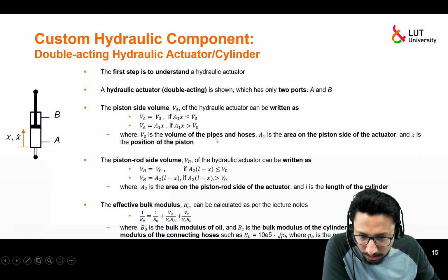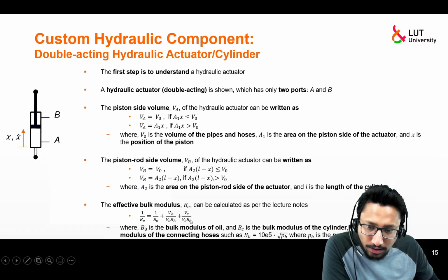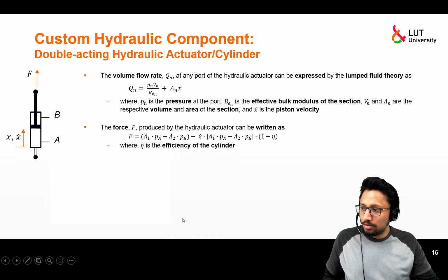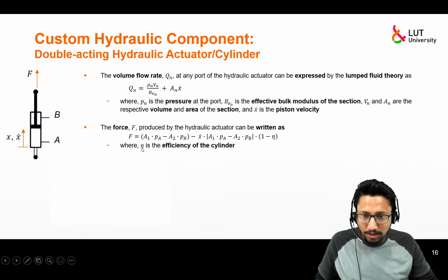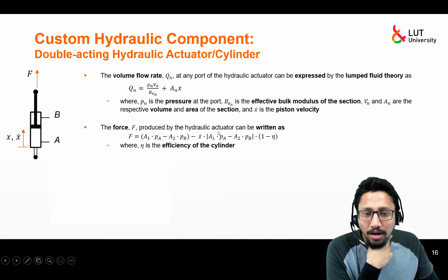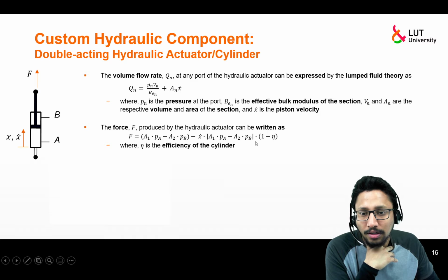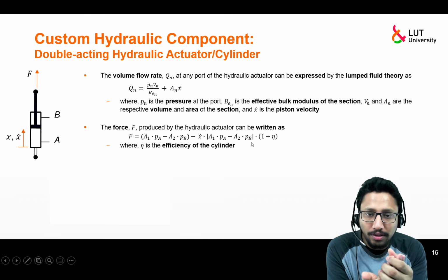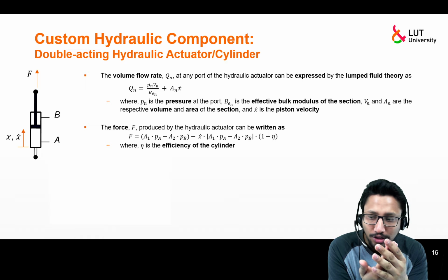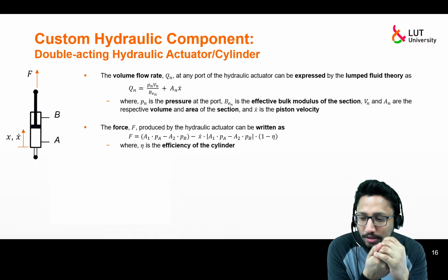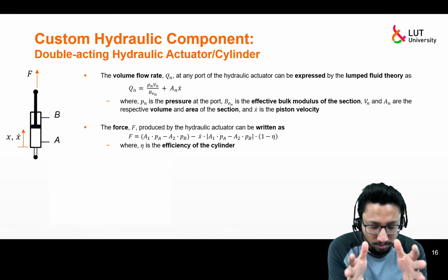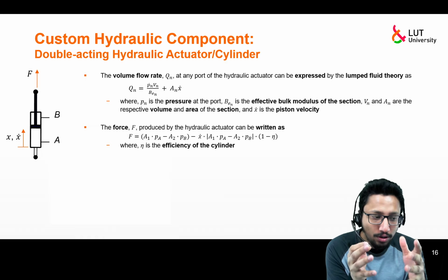Just a minute. So bulk modulus of the hose you need to calculate, whereas bulk modulus of oil and bulk modulus of cylinder are provided to you. And the efficiency here. Okay, so once you have understood these equations carefully, let's go ahead and start doing the coding and how we can do that.